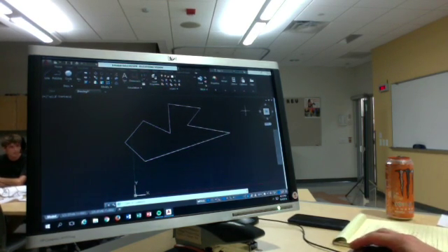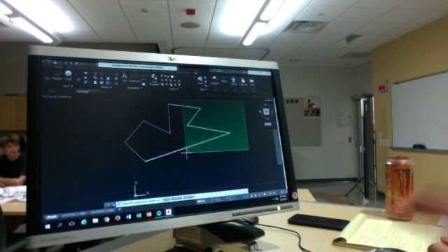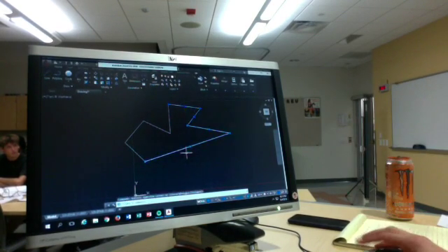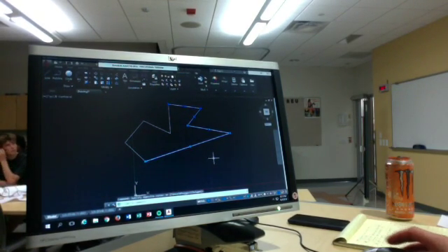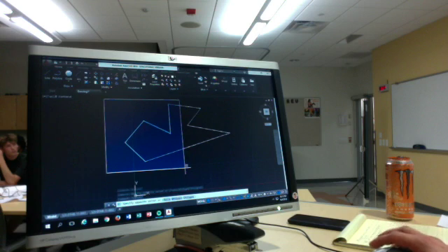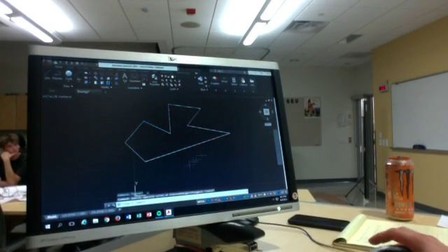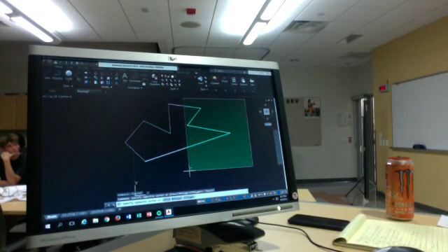When you draw a perimeter, you click. When you go to the left, everything within it and what it touches is being selected. But if you start from the left and go to the right, everything that's within it is selected. So you'll notice when I start on this side, these 4 lines are being selected because these are fully within it, but it's touching these.